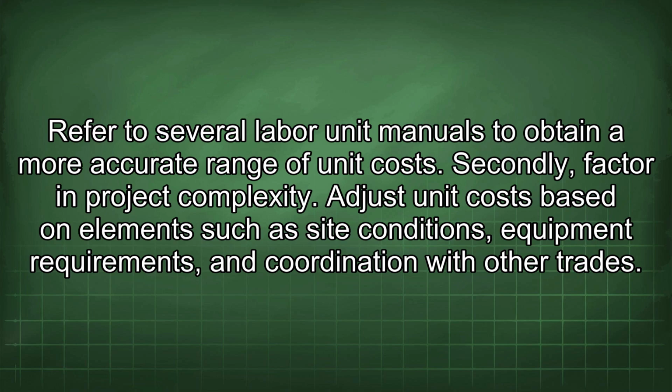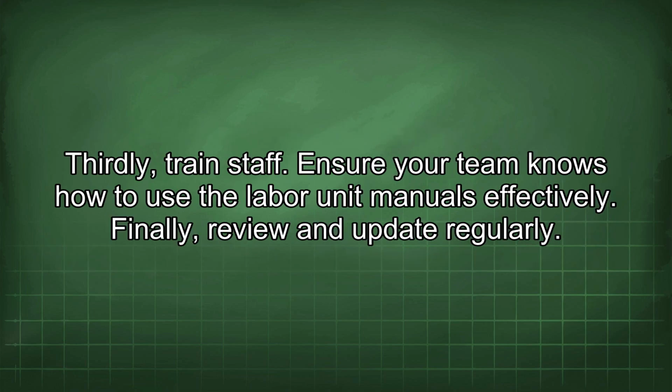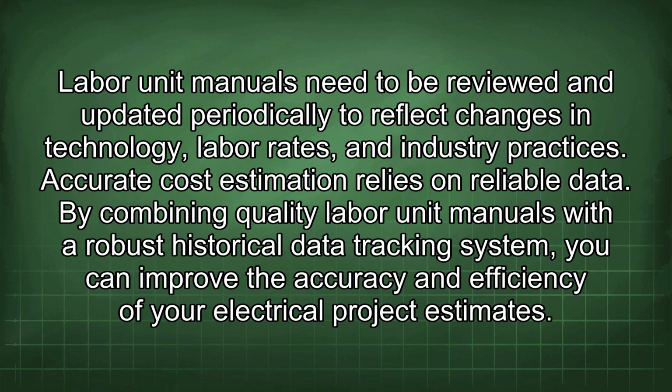Secondly, factor in project complexity. Adjust unit costs based on elements such as site conditions, equipment requirements, and coordination with other trades. Thirdly, train staff. Ensure your team knows how to use the labor unit manuals effectively. Finally, review and update regularly. Labor unit manuals need to be reviewed and updated periodically to reflect changes in technology, labor rates, and industry practices. Accurate cost estimation relies on reliable data. By combining quality labor unit manuals with a robust historical data tracking system, you can improve the accuracy and efficiency of your electrical project estimates.